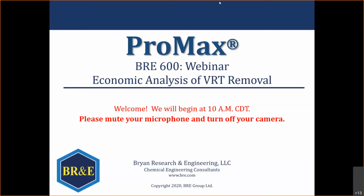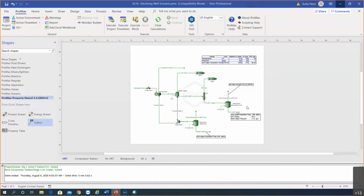In this webinar, which should take about an hour, we're going to take a look at a Wellsite, look at the advantages of having your VRT, and then how you could use Promax to determine whether or not you would still want to use a VRT, depending on the declining flow rate from your wellhead. So this is going to be our Wellsite, and on this first flow sheet, we can see a Wellsite with a VRT, but we're going to take a look at one without a VRT first.